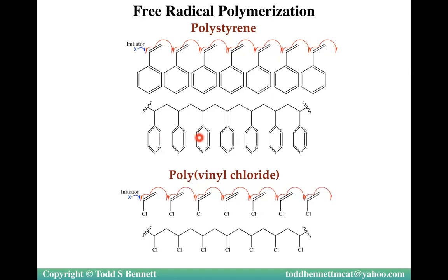So for this material, these rings are all kind of, I guess, jammed in together. It can rotate. It can do some weird sort of things in the way it packs with other polystyrene molecules. Polyvinyl chloride is much smaller, so it packs more tightly. So even though this polymer single strand might be very rigid, it's how it packs in with another one. So kind of like saturated and unsaturated fatty acids in cell membranes. Saturated creates more flexible molecules like this, but they pack more tightly, becoming a much more rigid or less fluid cell membrane. Same thing with polymer properties. The property of the individual molecules and how they interact affects one strand, but it may not affect how all the polymers behave together.